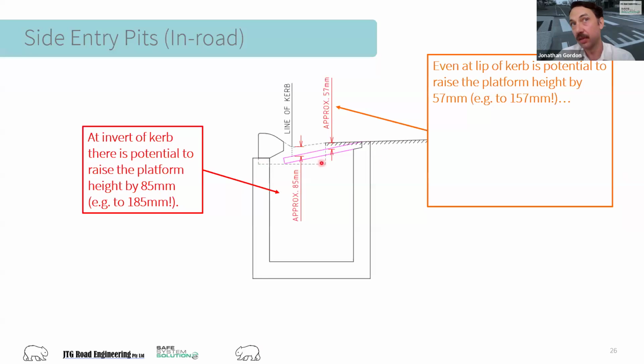Building it out, yeah. I mean, it could, but I'd suggest that if you have the room, the carriageway width to build it out and have curbs sitting further out ahead of this, then you might as well just keep the curb. If that width is acceptable for your design solution, then shouldn't it be acceptable potentially for your race safety platform carriageway width as well? And then you could put a back of curb side entry pit in place.